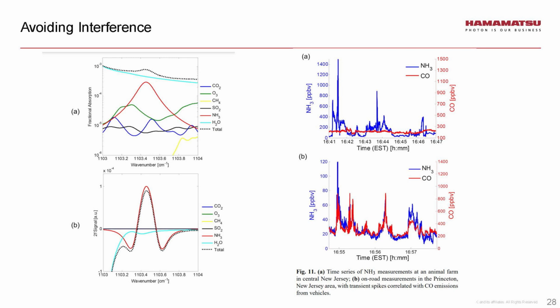And also to note, something that the research group found, as analyzers were placed closer to the road, smaller distances to the road showed massive spikes in carbon monoxide as well. So this just goes to show if there is an absorption band in the mid-infrared, you can create a system to find that gas and analyze that gas at extremely high sensitivity.